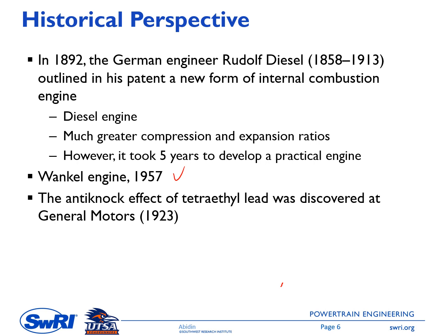It's also called the Wankel engine. So this is a rotary engine. The previous engine is a reciprocating type engine, in which the piston moves up and down. In this Wankel engine, the component of the engine rotates about the shaft at the center of the engine, so that we don't have any reciprocating component.